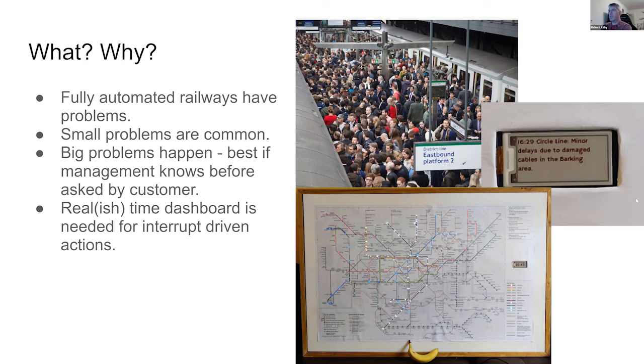So with the colors, you do have to correct for what's called gamma correction. You feed in a gamma correction string to allow for human perception of the light. If you're asking for 50% light or 50% of the power output for red, for example, it's not necessarily 50% PWM or 50% pulse width.